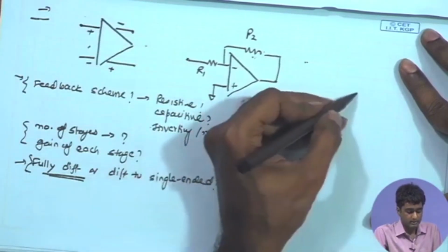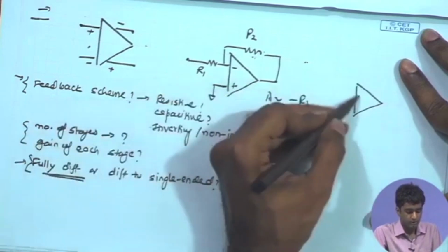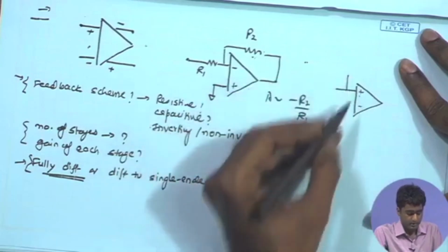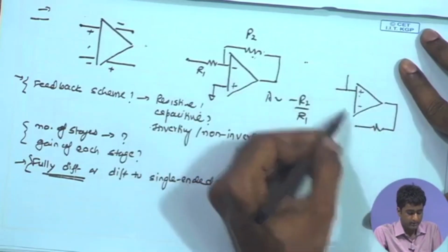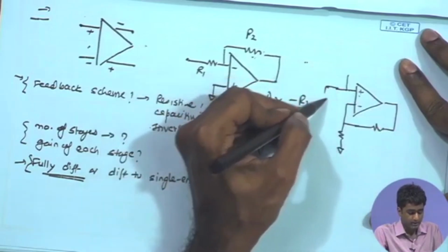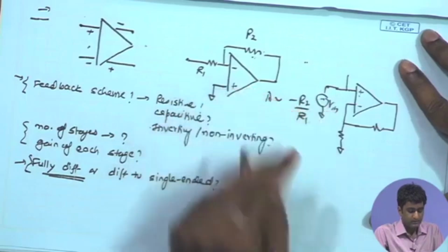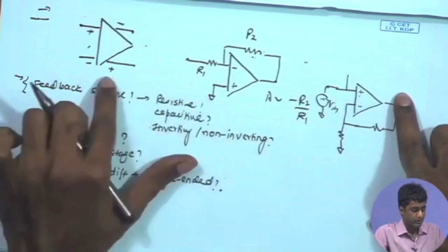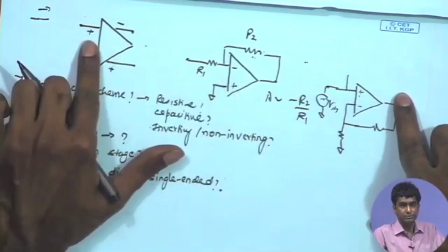However, if we look at, say, the non inverting configuration, where you are having the input signal applied at the main input and you are having the negative feedback coming at the inverting input, there is an interaction between the single ended output and the negative input, that will be difficult to implement using this topology.